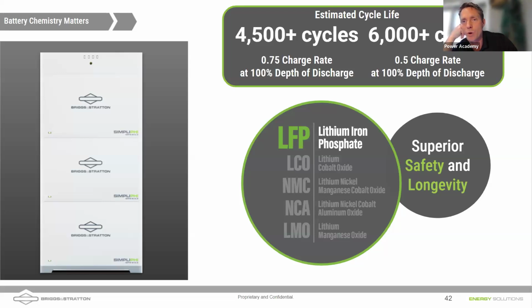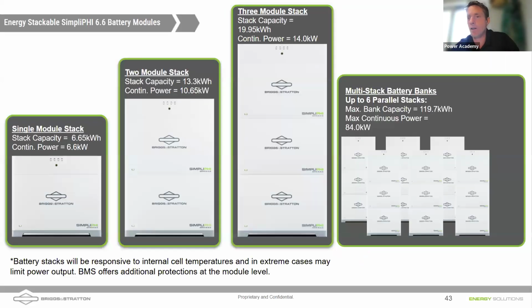Showing what the expected life cycle of the battery is based on a laboratory charge and discharge cycle occurring rapidly. But to answer your question, why charge rate plays a role is that it influences the temperature at which the battery is running. When you're running at extremely elevated temperatures, that does result in the electrolyte not lasting quite as long. So great questions. I point out this is mostly a residential battery for us.